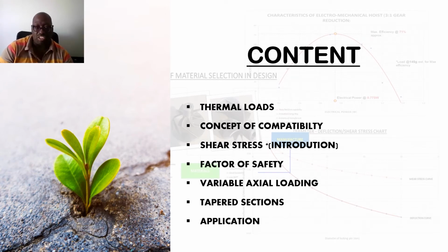From there, we also looked at the concept of compatibility. So if we have a situation whereby there is a measure of indeterminacy in a component, due to sections of it being constituted of different materials, or a change in the cross-sectional profile, then we can use these concepts to figure out what the measure of stress and strain is within the component.